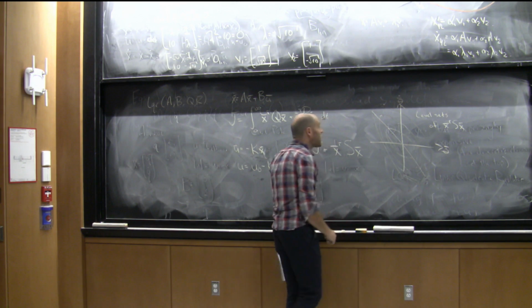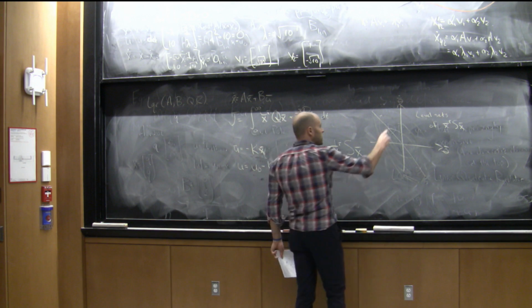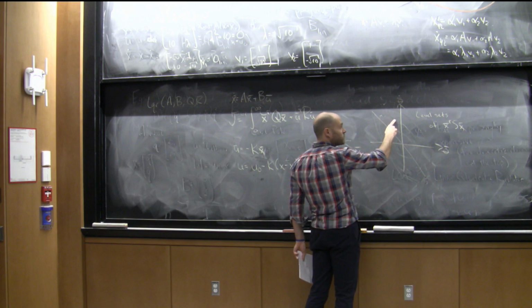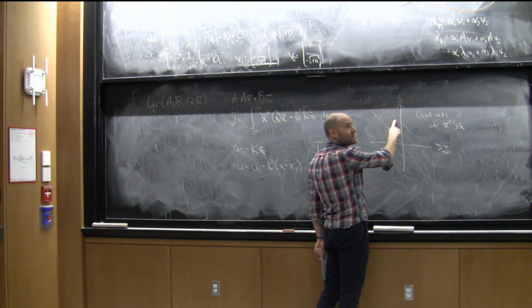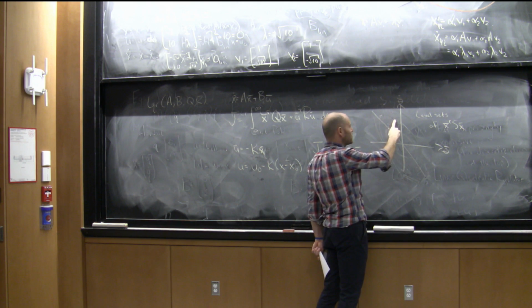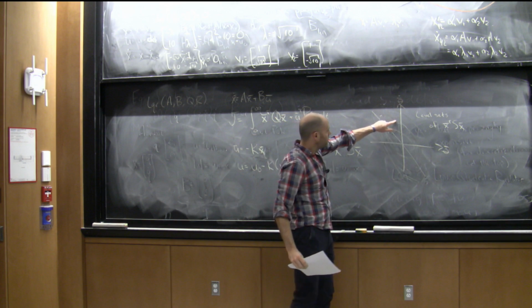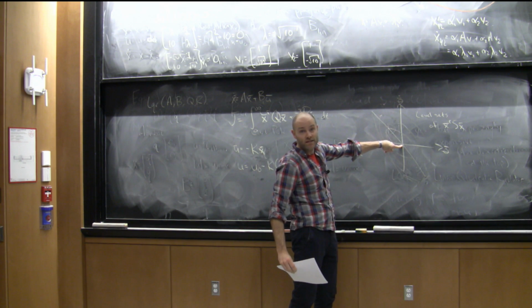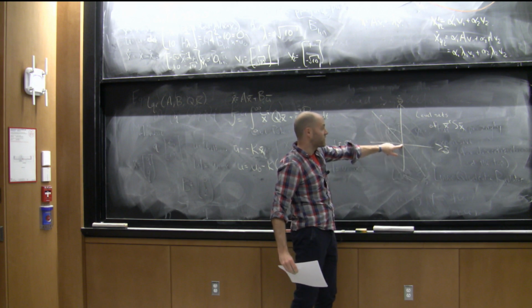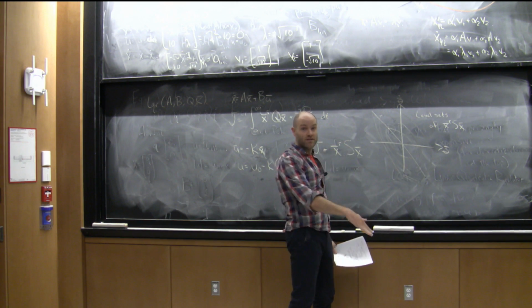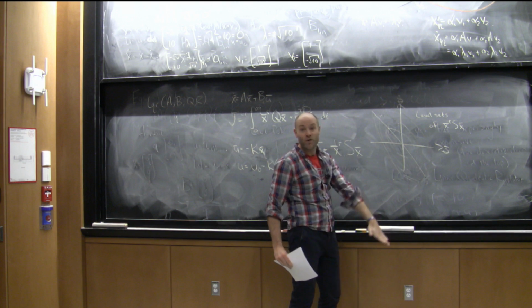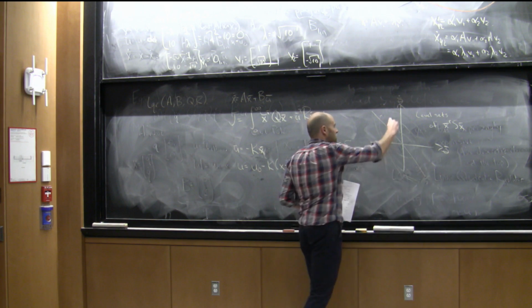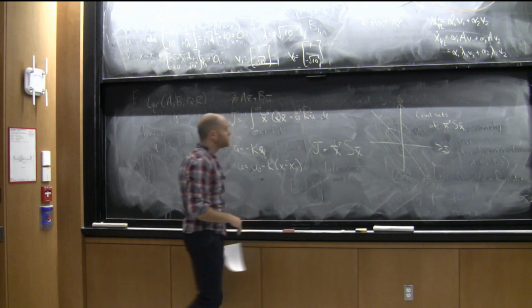Now, how long is it going to take this controller to get to the point there from right here? By the absurdity of the question framing, you should know there's an answer that sort of makes sense with that. It does not get here in finite time. It converges exponentially. A stable linear system will converge exponentially. So it doesn't reach there in finite time, right? It'll just get closer and closer and closer at an exponential rate. Okay, so these things will go down and get close there.